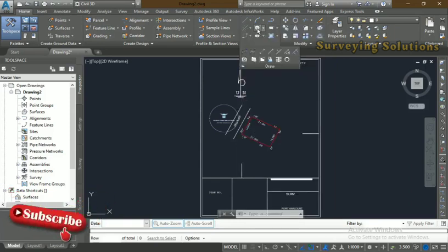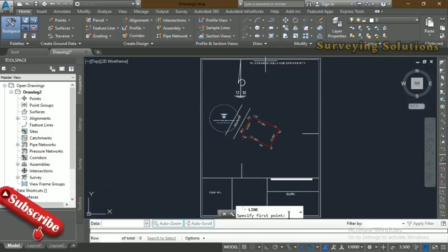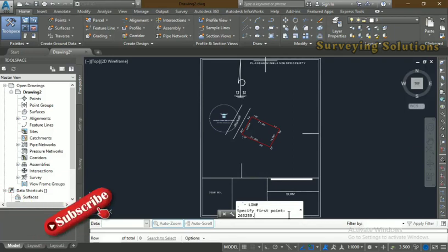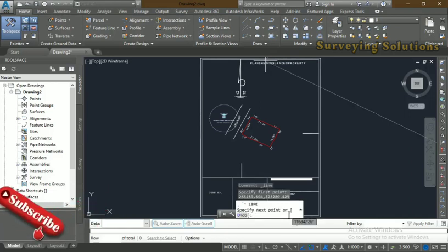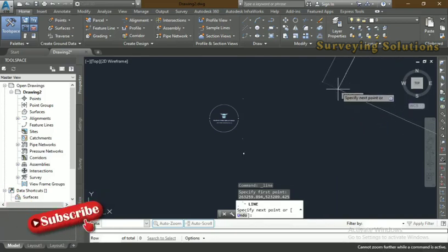Create line. Good. Specify first point. So the easting of the first point is actually 259.894. Then we have 523289.425. Good. So that's our first point. Actually a bit far from this place.